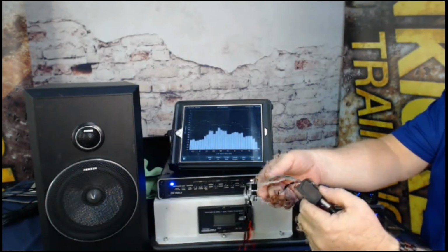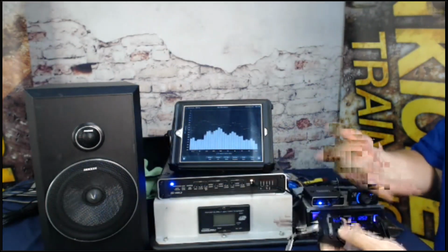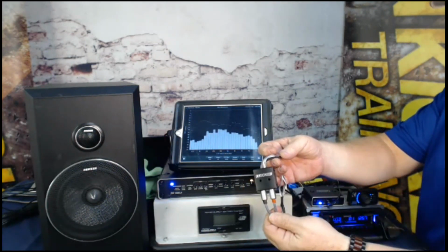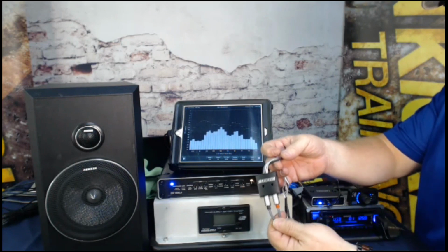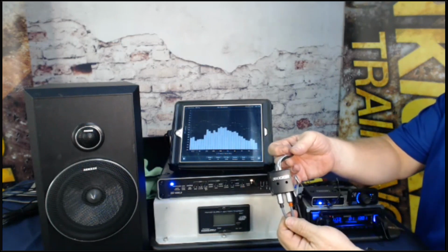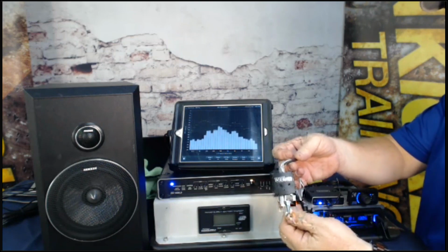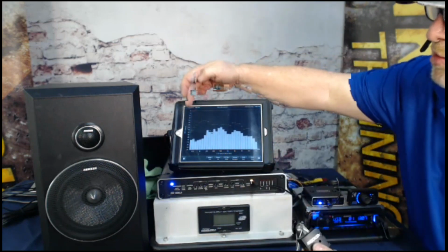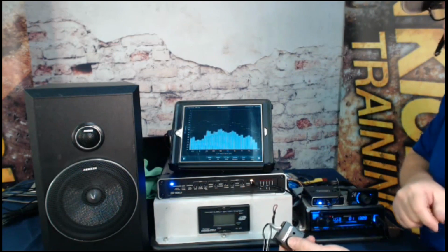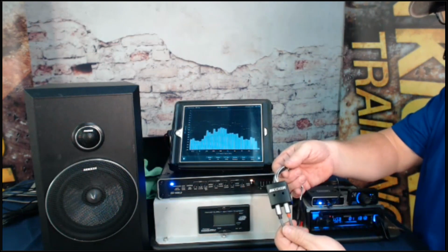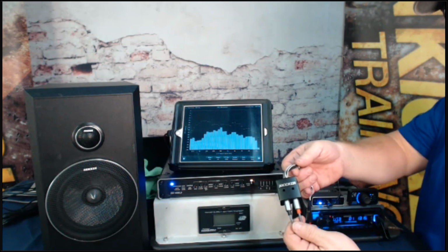The reason I suggest ours, not just because we work for Kicker, but we do, but a couple other reasons. This is flat frequency response from 5 to 50K with 55 watts power handling. Most line output converters, as you run more power through them, start narrowing the bandwidth, so you start losing the low and high frequencies, so it's not very accurate. These you can actually test at full power, 55 watts, still have a perfectly flat frequency response.